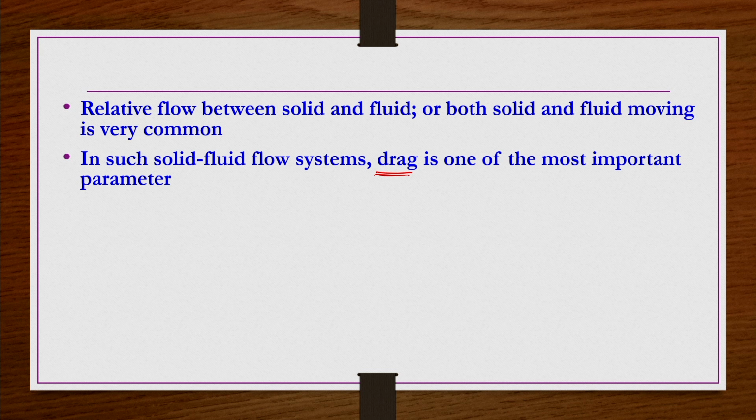So, either way, this drag is going to have a very influential role. Let us say in these unit operations, along with this motion, heat transfer is also taking place. Under such conditions, there is a necessity of having information about the Nusselt number as well. If there is mass transfer in this solid-fluid system, then along with drag, there will also be a need for the Sherwood number. That is the reason we might have studied several correlations for Nusselt number and Sherwood number in our heat transfer courses, right. You might have also seen some correlations for the drag coefficients.